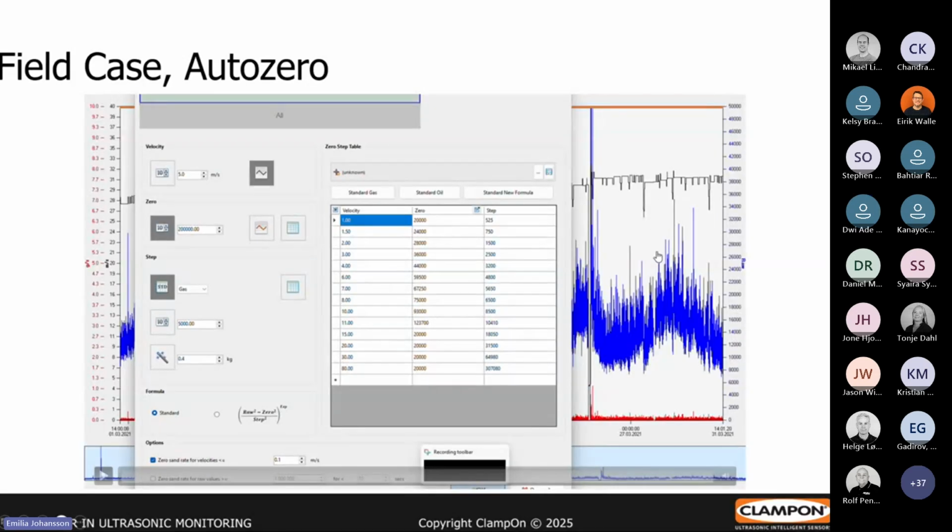The thing we often see is that we have changeable gas liquid ratio, which again causes changeable background noise level, and that causes an issue because you might not see it on the calculated velocity. That's not varying even if the gas liquid ratio changes, but we see it on the acoustic.